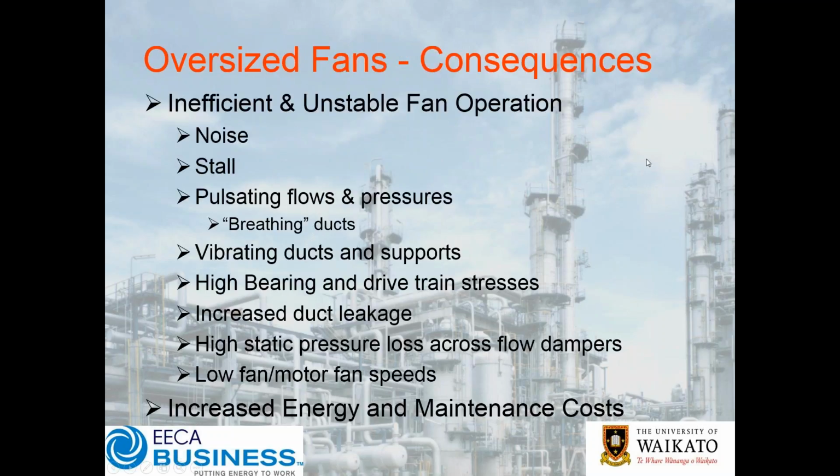So what's the consequence of being lazy with our design or being too conservative? Well, ultimately, we're going to end up with an oversized fan, which is going to ultimately be inefficient and unstable to operate. We're going to have a lot of noise considerations. The fan may be running close to stalling. It might be pulled right back. It might be in an unstable part of the fan curve. Quite common to get pulsating flows. Our pressures might not be all that stable. We could be at a part of the fan curve where a small change in pressure can make a big difference to the flow rate delivered.